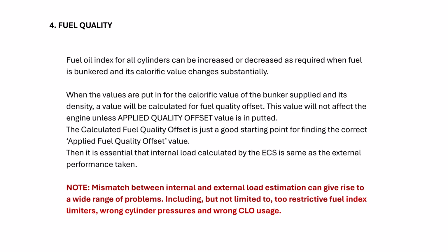Fuel quality. The fuel oil index can be increased or decreased as required when fuel is bunkered and its calorific value changes substantially. Naturally, when you take bunker, the calorific value of the fuel is different. Remember, the system calculating values in your ACS is based on a certain calorific value. You can calculate the power developed by your engine by finding out how much fuel is being consumed. But in that case you take some calorific value. If you do not know the calorific value, or take some arbitrary value, the power you have calculated will not be the correct value. So you have to know the correct calorific value.